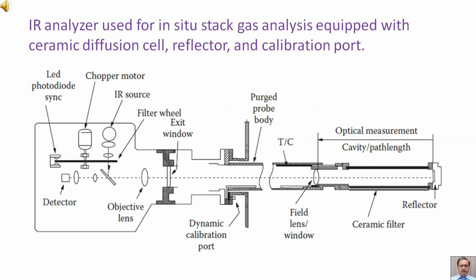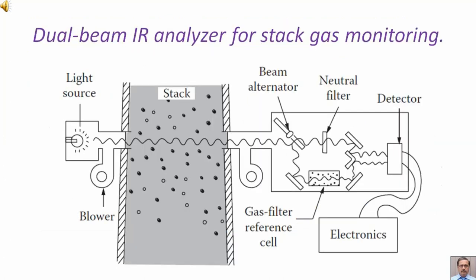Infrared analyzer used for in situ stack gas analysis, equipped with ceramic diffusion cell, reflector and calibration port. Dual beam infrared analyzer for stack gas monitoring.